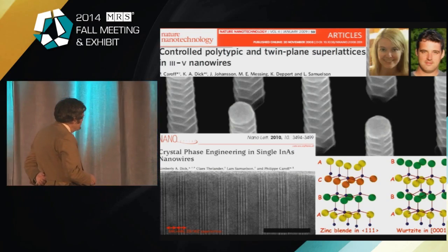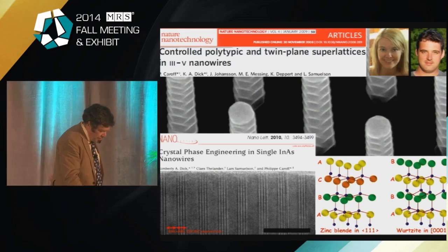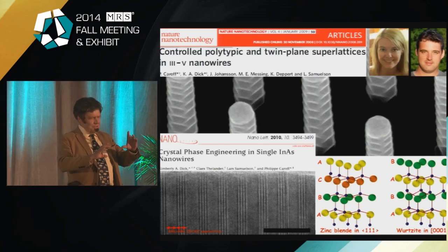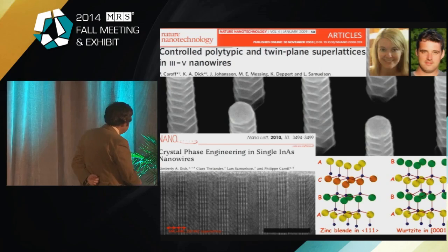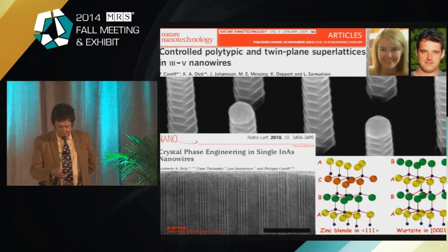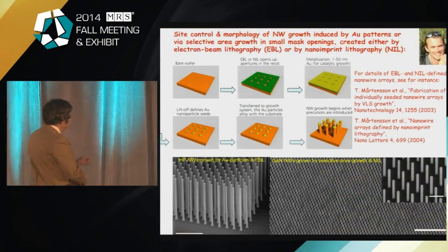And here you see a superlattice that is all indium arsenide, but with 8 monolayers of the zinc blende, 8 monolayers of the wurtzite, 8 monolayers of the zinc blende into a perfect superlattice, and that makes it quite an interesting system for semiconductor guys, like some of us, since these are type 2 band offsets, which means that you form these short segments, like the zinc blende, that are attractive to electrons, and the short segments that are attractive to holes, and you get pretty interesting optical and transport behaviors.